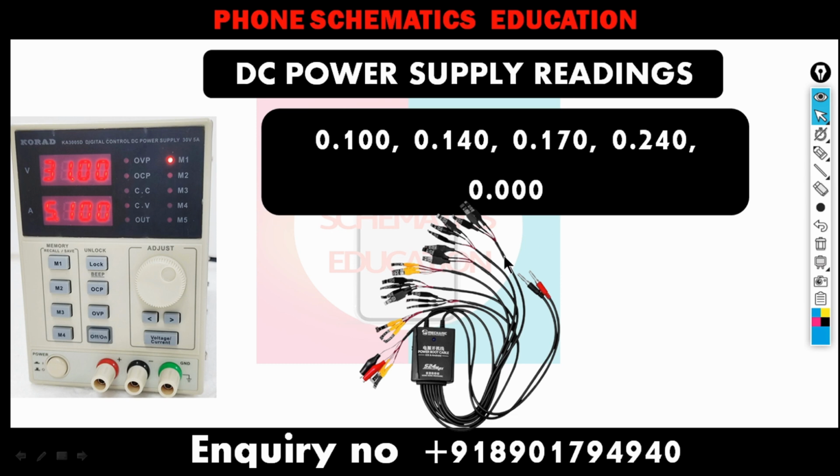In some phones, your DC or your boot cable, obviously you connect with the boot cable, right, this boot cable is not compatible. See, if the circuit, let's say the battery ID identification circuit, does not work, sometimes you get a restart-like reading because the circuit is not compatible. So it shows a fake reading.